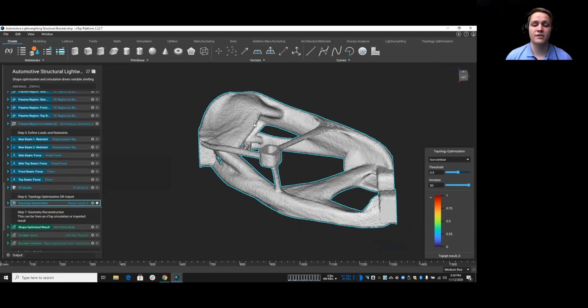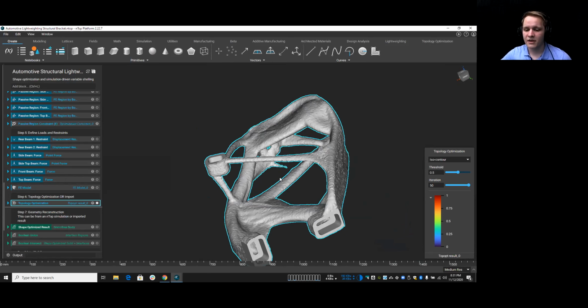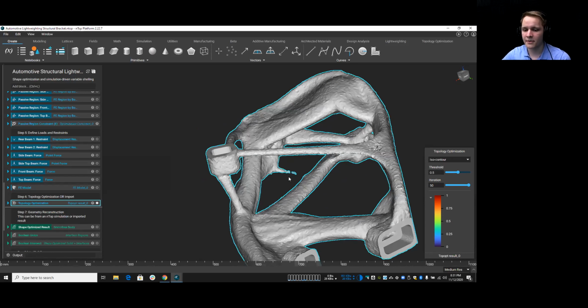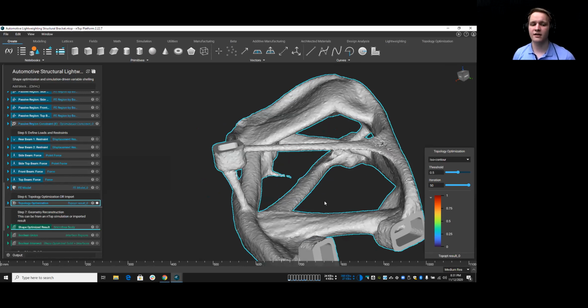And in your legacy tool, this work's going to take you hours. It's going to give you an STL file. You're going to have to try and do mesh smoothing. That's in most tools, at least, but it's not a fun process. Trust me, I used to do it a lot. The second part is, maybe in our optimization process, we have some geometry here that's too thin, right? It's not connected to anything. It's not usable either. And normally, if you see this issue, you're going to have to rerun your entire topology optimization so that this will bump up. You're going to have to up your volume fraction, rerun a whole new top opt. Not what you want to do.